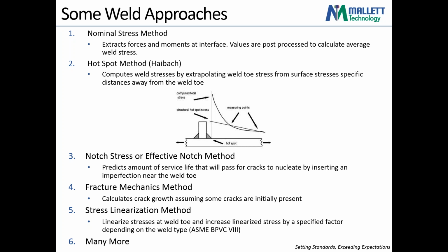A similar method to that is the fracture mechanics method. This assumes certain cracks at the weld toe, and then based on the loading, it will make a prediction on how quickly those cracks will propagate and eventually cause failure.